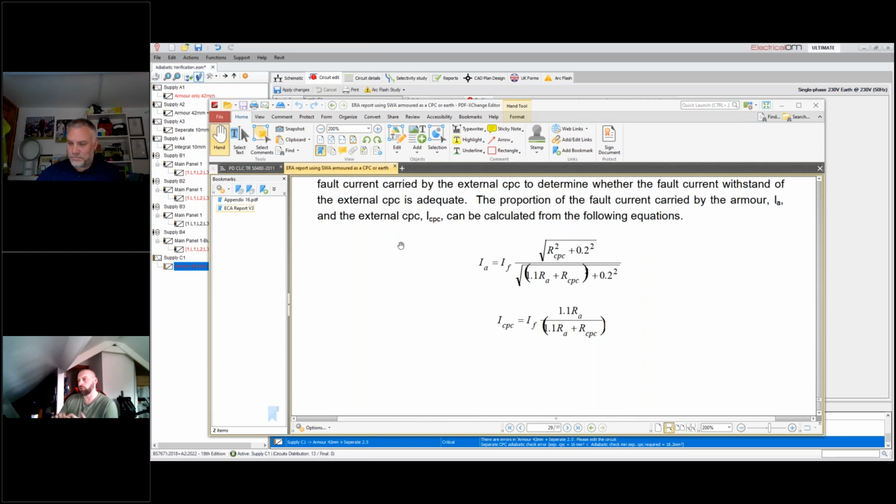So your protective conductor can be made up as a combination of those. It doesn't specify that it has to be one or the other. But when you are making it up as a multitude, the fact that you've got two different materials there is our consideration. The primary place where we get this is the armour. The armour is probably the most onerous of these.